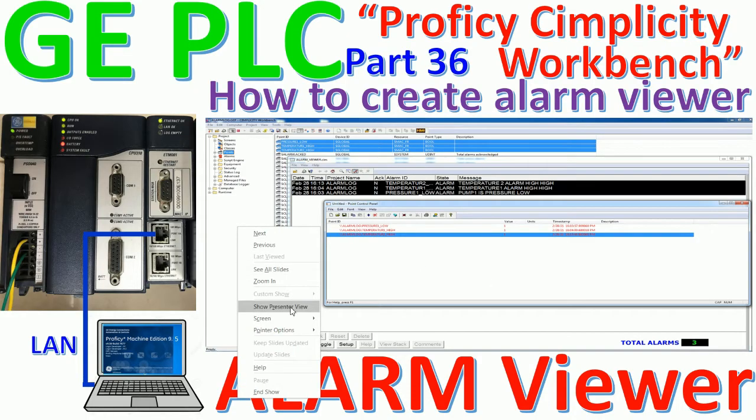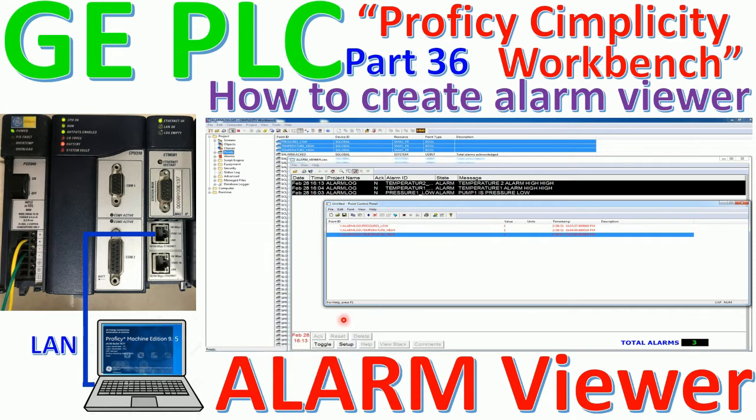Today I would like to show and share about PLC and SCADA software, about how to create the alarm viewer by using software Proficy Machine Edition and Proficy HMI Workbench. Okay. So here is the example that I already created the alarm for show. Example, temperature number 1 is high, temperature number 2 is high, or pump number 1 is pressure low.